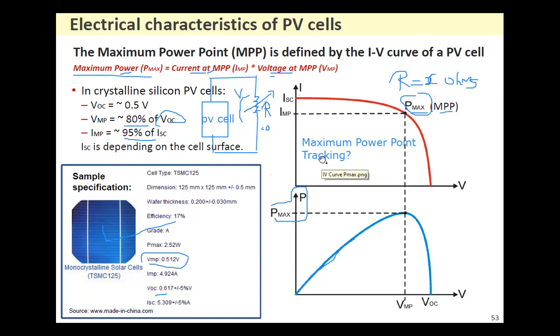So what happens in real time for the maximum power point tracking is that your controller looks for that point and modifies the resistance across the panel in such a way that it is ensured that you are getting maximum power out of that panel, because you can see here the voltage is more but the current is less.